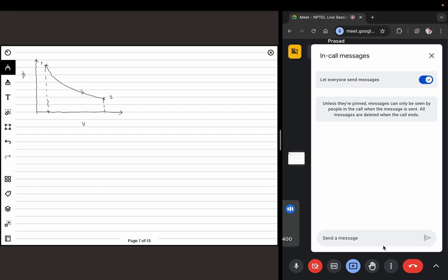If you are aware of any numerical integration techniques, you can use them. Or if you are using Excel or something, you have different points at which the data points are given. You approximate that in between them it will be linear, then calculate the area of that particular trapezoid, and keep adding all these areas to get the total work done. That will be a rough estimate. That could be another way of doing it. So either perform numerical integration.